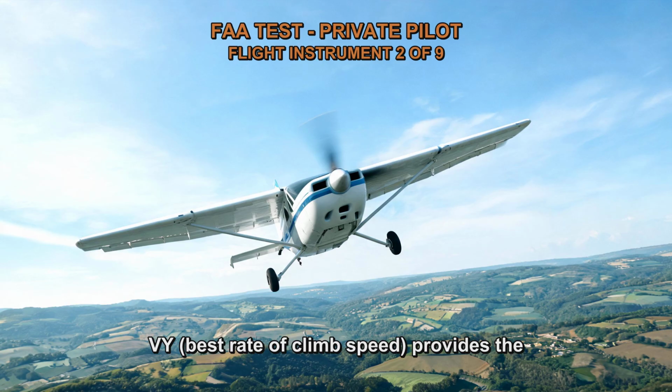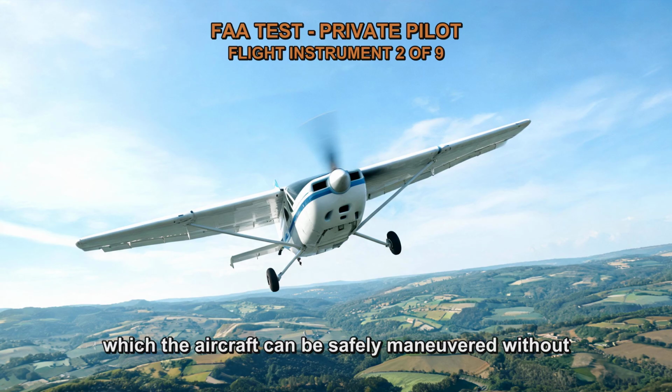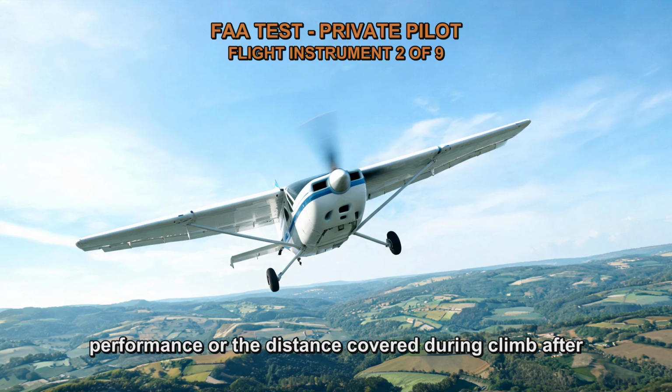Vy, best rate of climb speed, provides the greatest gain in altitude per unit of time, but not necessarily in the shortest distance. Vy is typically used during a climb after clearing obstacles and when the priority is to gain altitude quickly. Va, maneuvering speed, is the maximum speed at which the aircraft can be safely maneuvered without exceeding its structural limitations. It is not directly related to the climb performance or the distance covered during climb after takeoff.